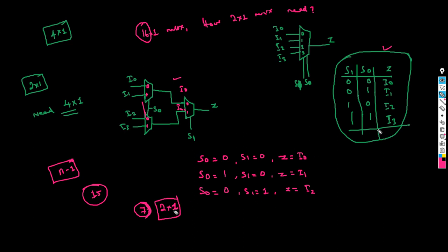Okay, all right. Now, we were talking about mux being a universal gate, correct? Can you quickly design, or implement using mux? My request is, say I need an inverter, but I don't have an inverter with me. I have only a mux with me. Now implement an inverter using mux, and then a buffer, and then an AND gate, and then an OR gate. Can we quickly do this?